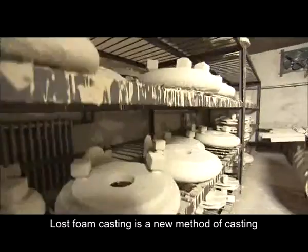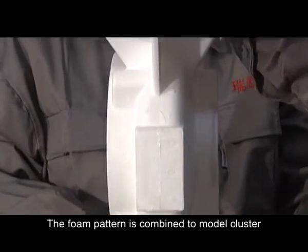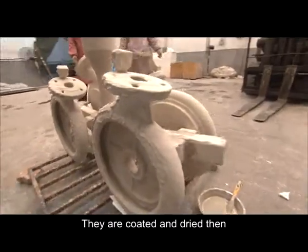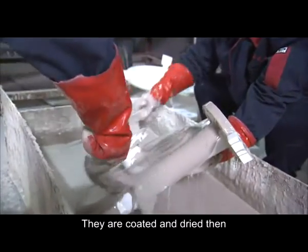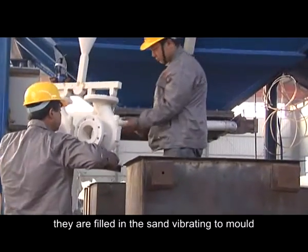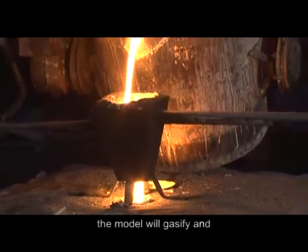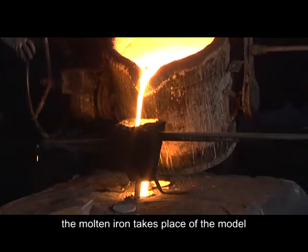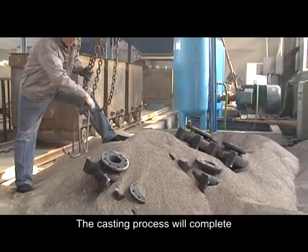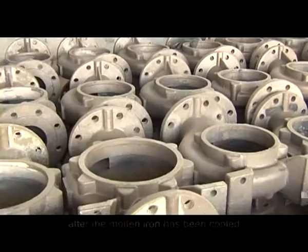Lost foam casting is a new method of casting. In the process of casting, the foam pattern is combined into a model cluster. The model cluster is coated and dried. Then it is filled in the sand and vibrated to mold. The casting takes place under negative pressure. The model will gasify and the molten iron takes the place of the model. The casting process is complete after the molten iron has cooled.